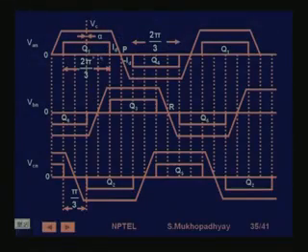move. So, we are switching these transistors Q1, Q2, Q3, Q4 in such a manner that they always, so you see at some interval Q1 and Q6 are on, then in this interval also Q1 and Q6 are on, and this is off, and in the next interval Q1 and Q2 are on. So, Q6 has been switched off. So, in this way we are actually switching the stator MMFs and keeping always the torque positive.